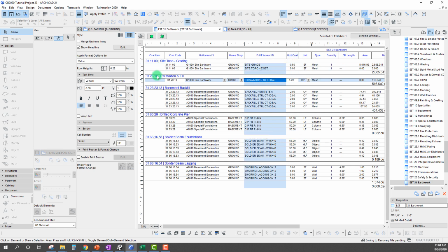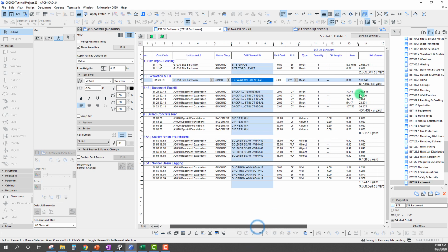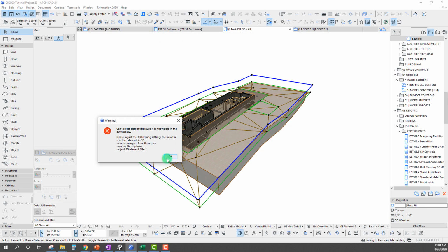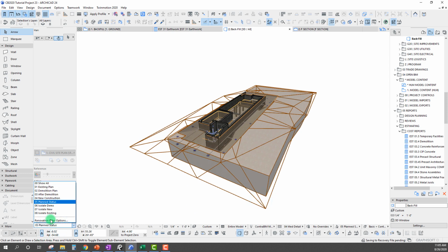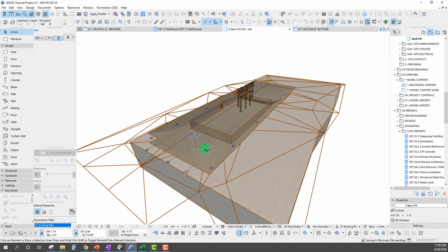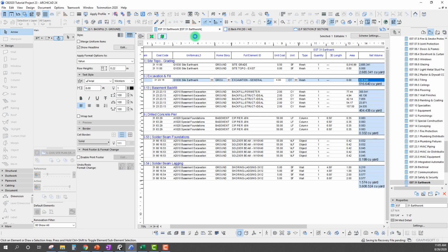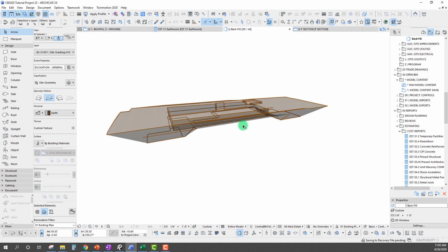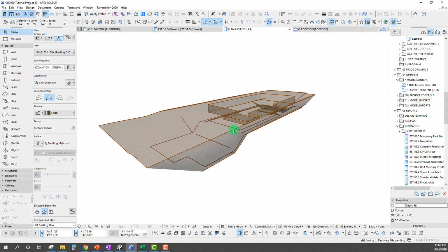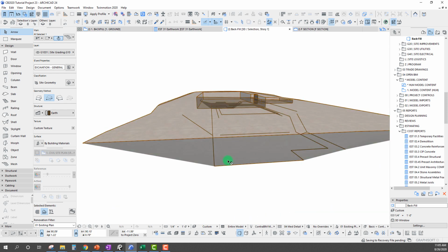And then, of course, we have our excavation and fill here. So we can see we have a total of 516 cubic yards in this case. So we can highlight this. Okay, we can actually see that it's not necessarily turned on because we're on our plan status. So if we go to an existing plan, then we should be able to highlight this. Okay, there we go. So this would be our basement excavation, not a mass excavation, which includes our sloping to get down.